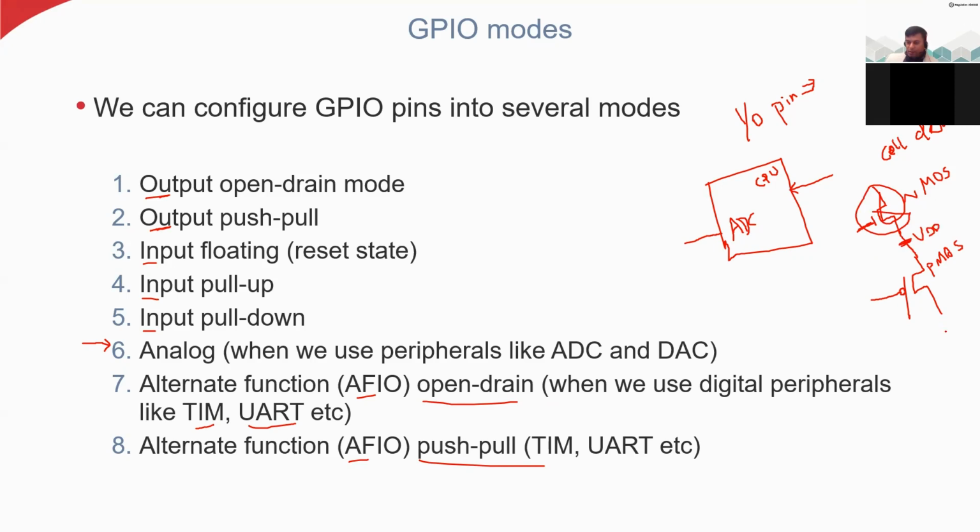and here you have the NMOS, and this is grounded, and you can just connect these two gates together and apply the input. So you are applying the common input to both gates. For example, if you apply 0, then what will happen? 0 will always turn on the PMOS transistor.